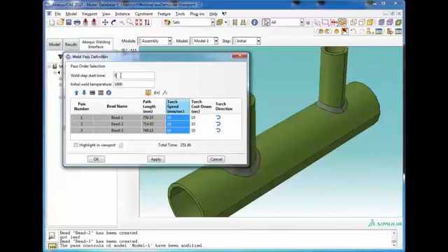Now there are 2 items up here, the weld start time, if you want to have a delay. In this case we're putting a big weld down and a small weld, so we could put in delays for when one of the welds starts. By putting in 0, it just says it's going to start immediately at the beginning of that step. And then the initial weld temperature, which you'll notice looks like the stress cutoff temperature, is the initial temperature at which a weld is inserted. When we activate a weld element, it's presumed to be activated at or near melt temperature. So the default is this 1600, the stress cutoff temperature.